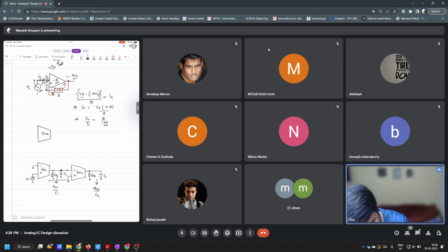And if you have two poles which are very close to each other, what happens? Basically you will have this kind of loop gain curve. It will have some DC gain. What will be the DC gain here? It will be gm1 divided by go1 into gm2 divided by go2, correct? And then it will have this first pole p1.